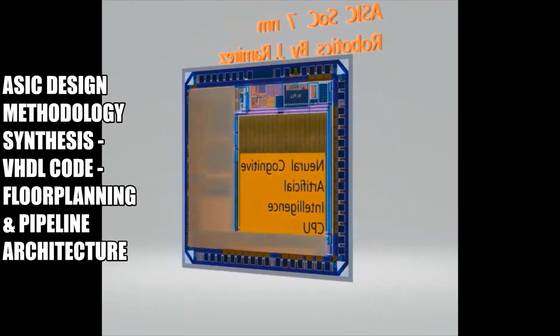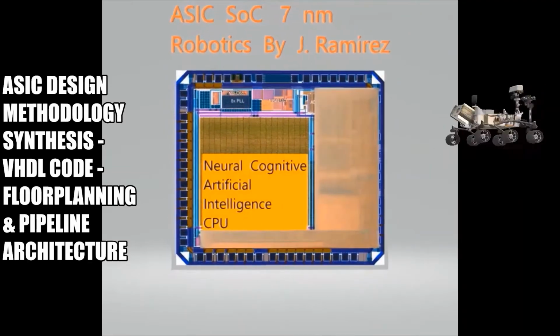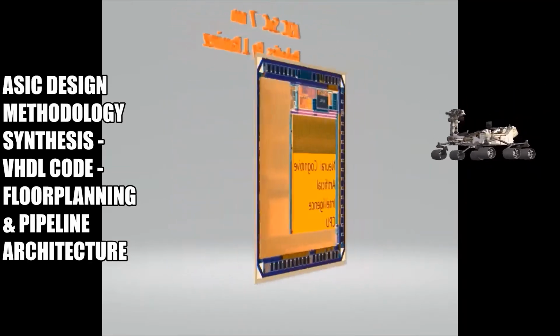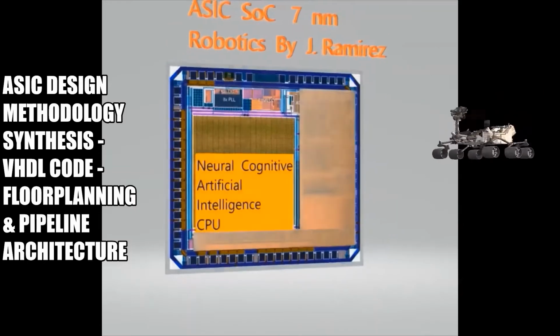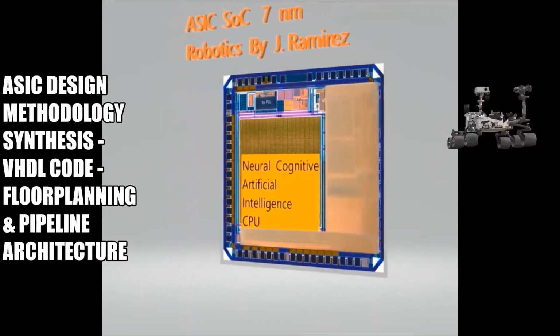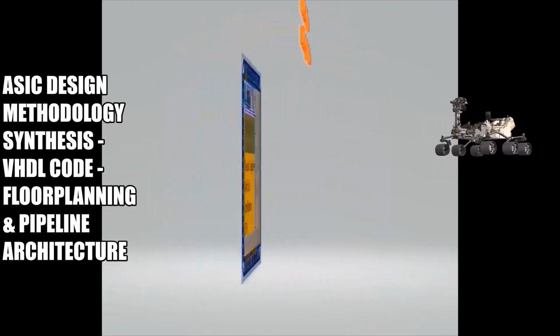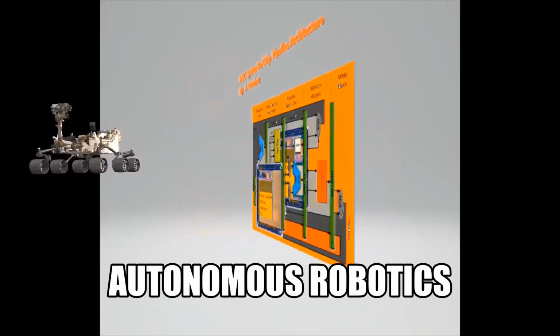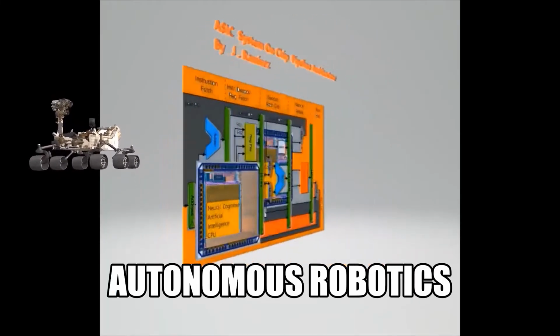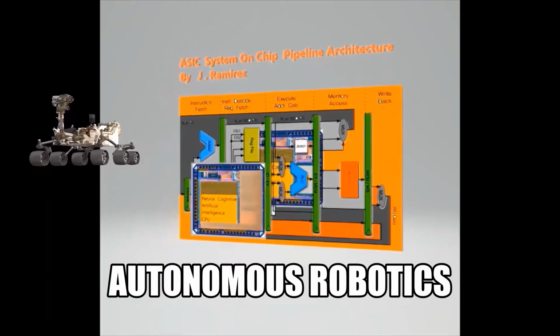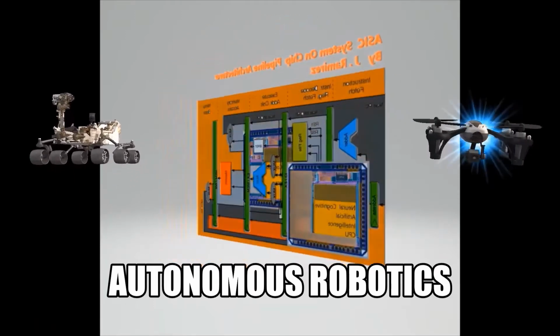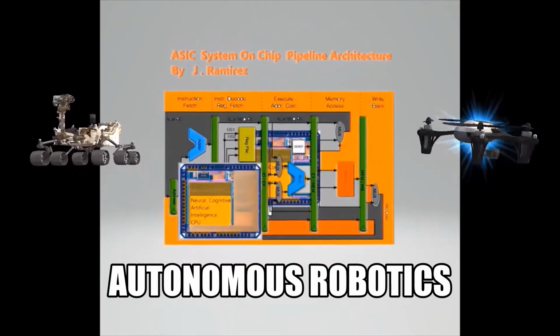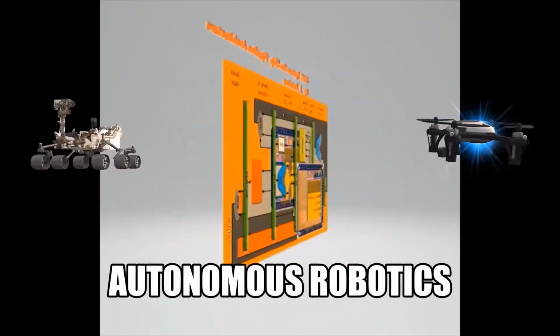Clock optimization and scan optimization processes are applied to improve timing, wiring, and clock skew. Clock optimization modifies the organization of the clock tree buffers and the clock splitters according to the layout of the latches.